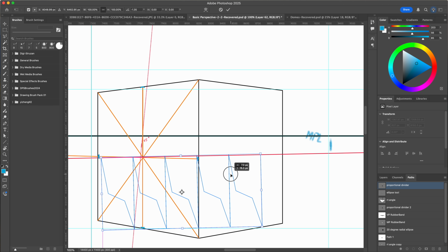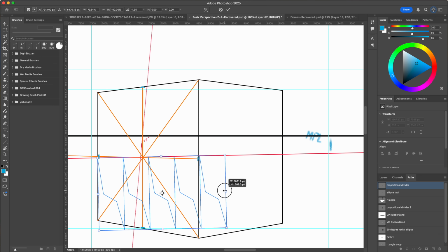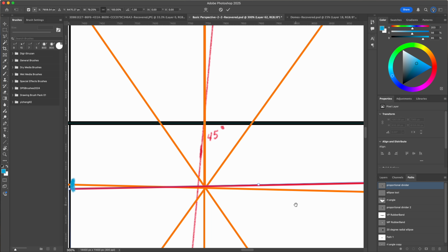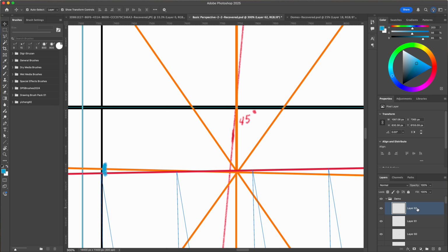So if I go ahead and grab this and I put that point there on the right-hand side of where the minor axis crosses that face right there. And then I can scale this edge here to where it hits the right-hand side of that face. That's going to give me this point right here, which is our measured center of this face. Okay, so let me go ahead and do this, and I will mark this right here. So that's the measured center of what will eventually be our ellipse.